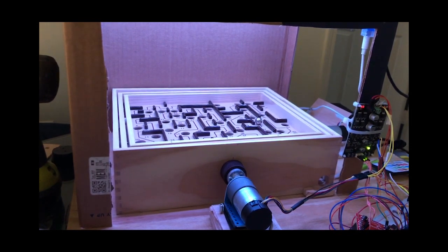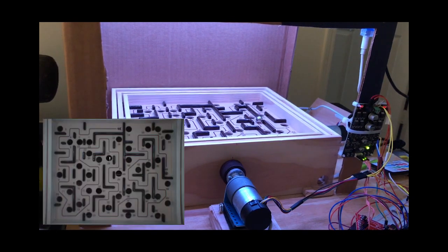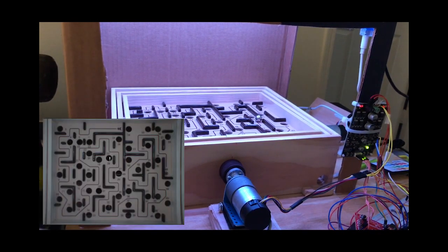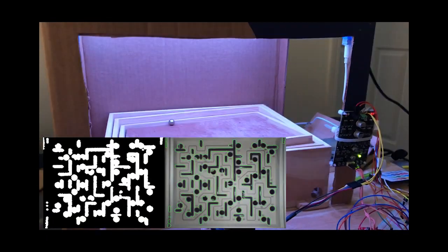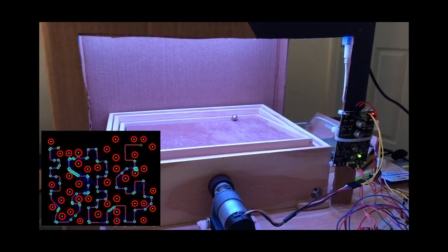The computer vision consists of initially taking a picture of the board from above and using hue, saturation, and value to draw contours of where the walls and holes are. This will help us avoid dangerous areas for the ball to go. We then use edge detection to detect the guiding line that leads through the course, and with this line we can then place nodes along the course where the ball should find itself on the way to the final objective.